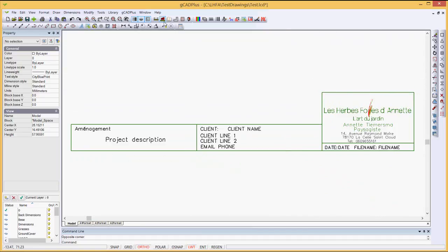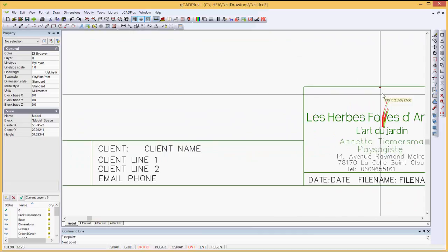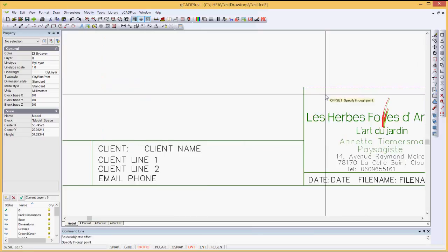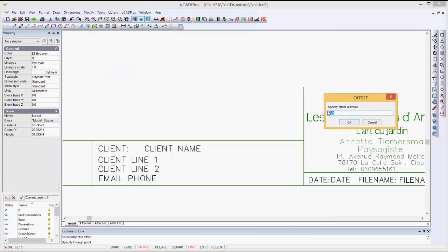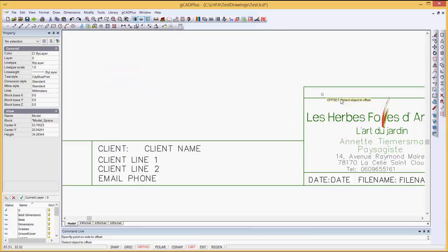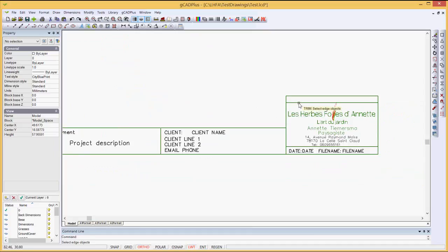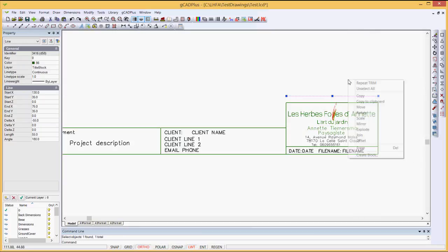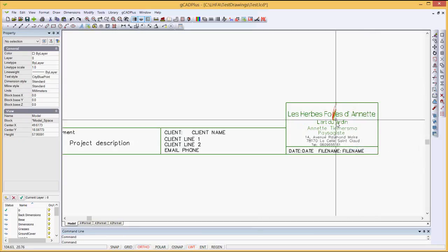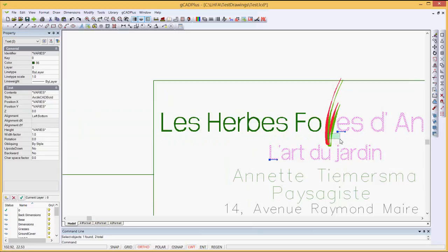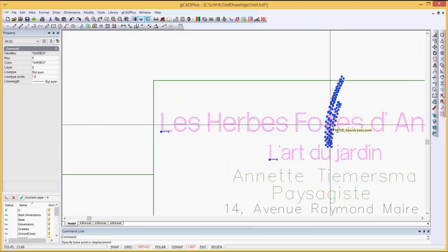I'm inclined to bring that down a little. I'll offset that line, I think, by about 5 mil. So I'll just check in here from there down to about there. 4 mil might be safer. So we'll go modify, offset this one, right click, distance 4, okay, put it down like so, and then modify and trim again. This is the cutting edge, and trim off that one, and then select this one and erase it. Just zoom in there and see whether we've got our clearance correct, and we haven't quite got there.